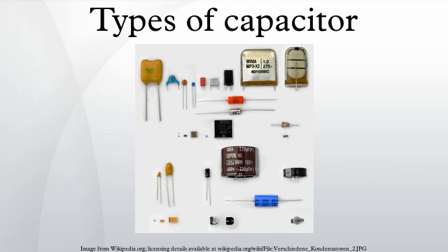Long-time behavior, aging. Electrical parameters of capacitors may change over time during storage and application. The reasons for parameter changes are different. It may be a property of the dielectric, environmental influences, chemical processes or drying out effects for non-solid materials.